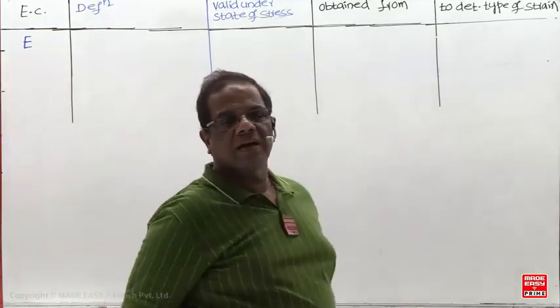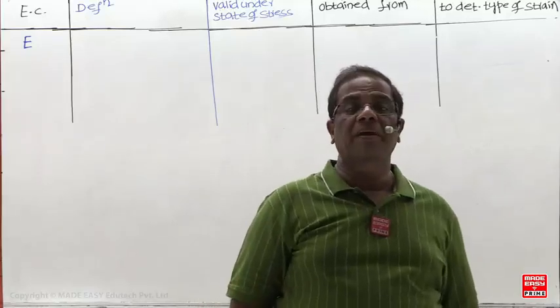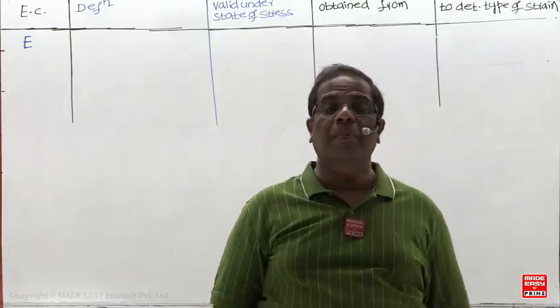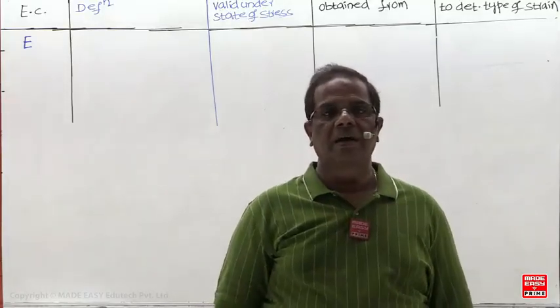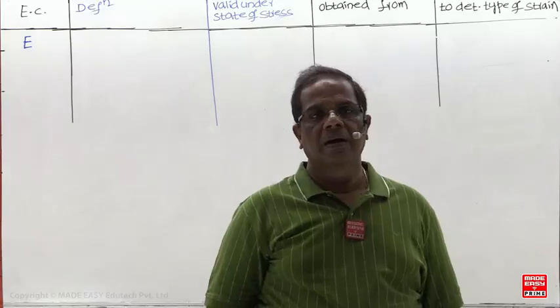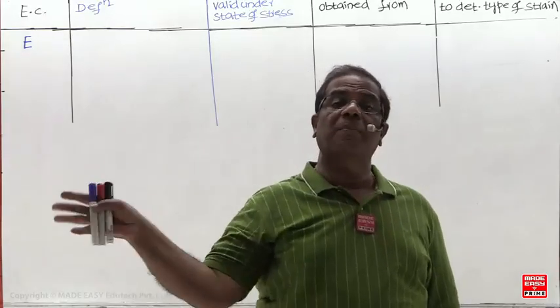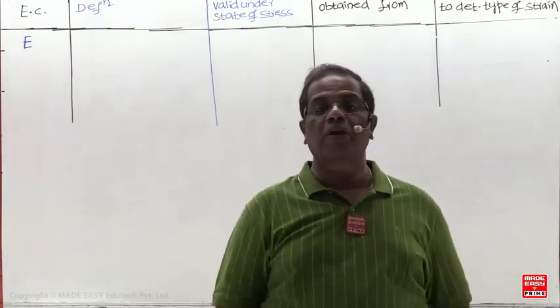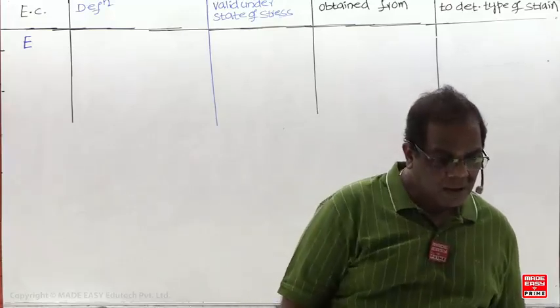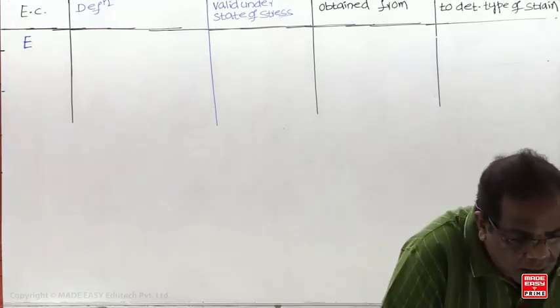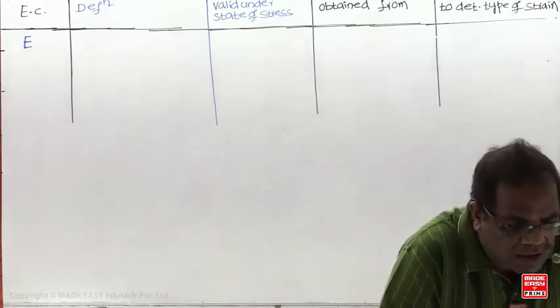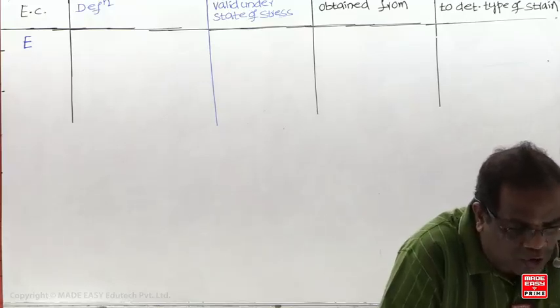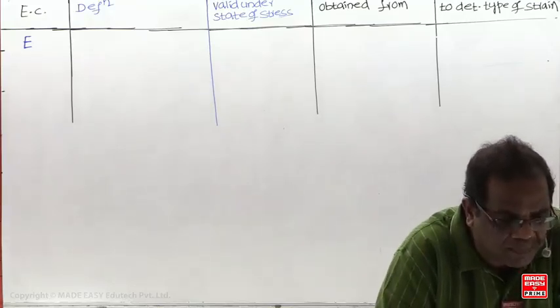Anisotropic means what we have studied now. A material is anisotropic when it exhibits different elastic properties from direction to direction. At a point, how many directions are there? Okay, sorry. Probably I wrote anisotropic; change it to orthotropic.